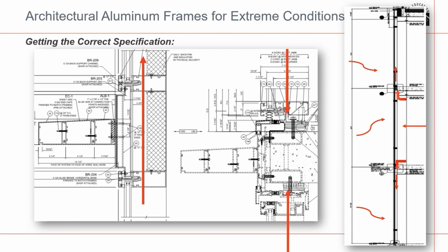The detail on the left is a curtain wall application that would be fine for a commercial project, while the detail in the center is showing a window wall system, which is the detail you want for a high-rise multifamily system. This detail and system application is designed to prevent sound moving from one floor to the next, and at the same time stop sound moving from the exterior to the interior. So you're focusing here on interior acoustical performance or interior occupant comfort.